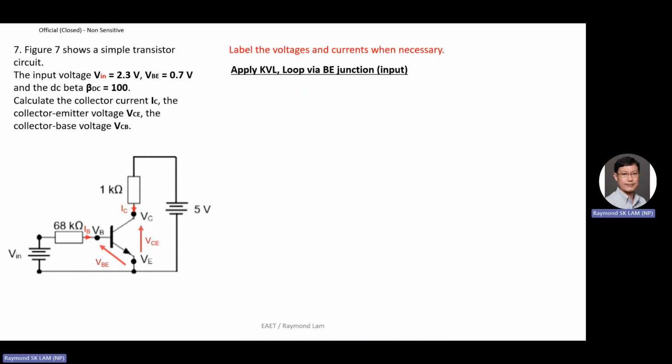To repeat, the current input here is the input. Down here we have a voltage source, for example 5 V. The current flowing down here, this IC, is the output. When you plug in a small current here, the transistor will amplify the current, so that IC equals beta IB. Beta is called the current gain. Normally it's 100, 200, so it will amplify the current.